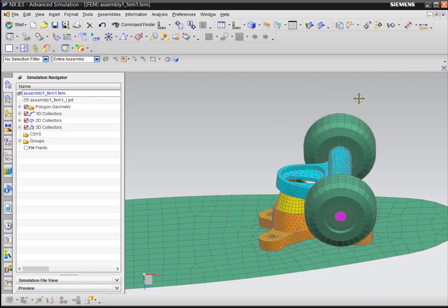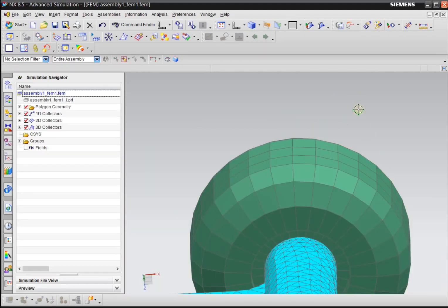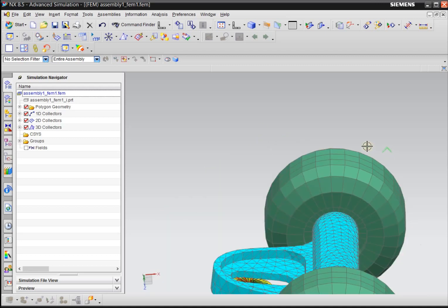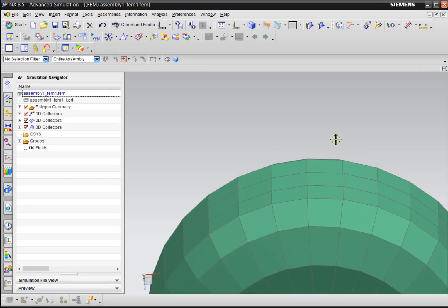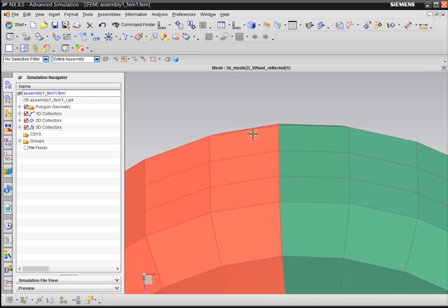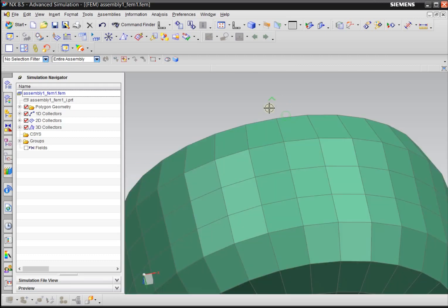So we can actually grab the center of the spider, then further grab this small area of nodes. So again, for spiders, first we're going to create a center node, and we want the node to be in the center of this line.